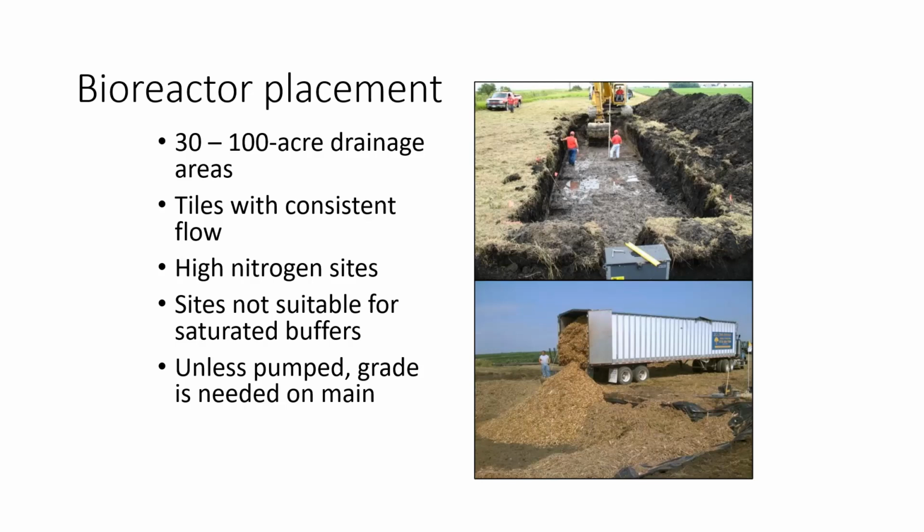But if it's a tile line that generally does not carry very high nitrate concentration, perhaps there's some other practices that you could consider instead of a bioreactor, where you're not going to have that 10-year maintenance interval on it. Bioreactors are kind of the generalists when it comes to where they fit in the landscape. They're very flexible in where they'll actually work.